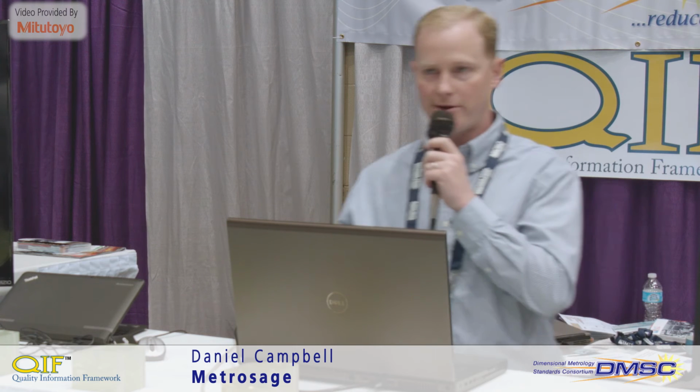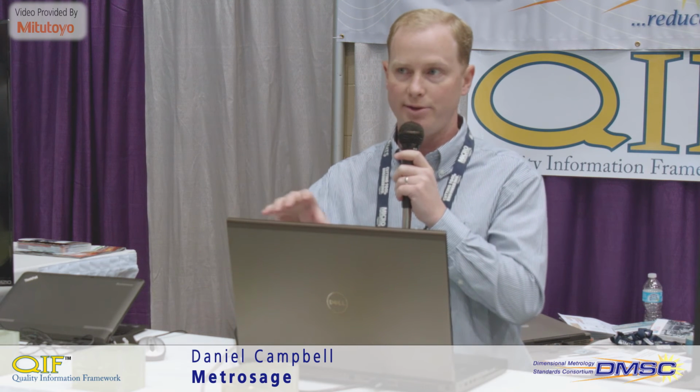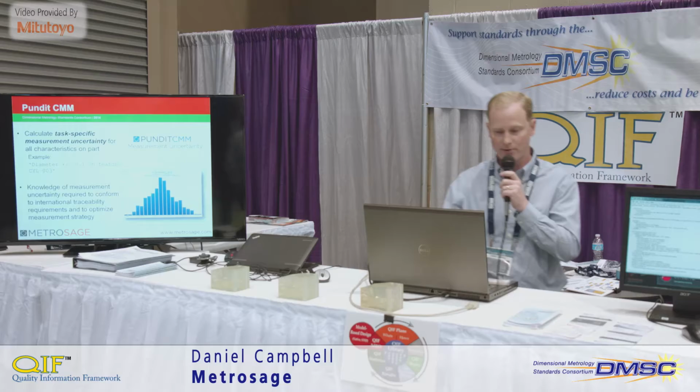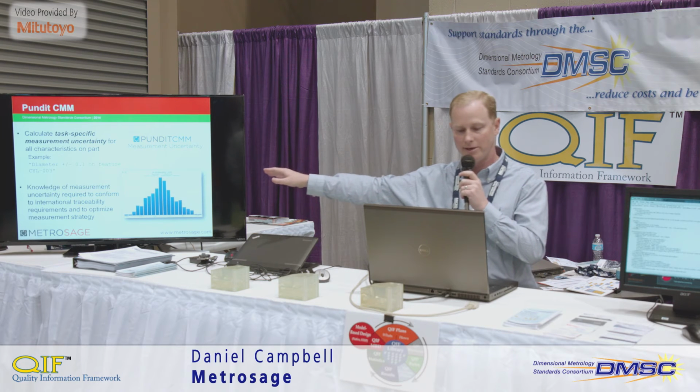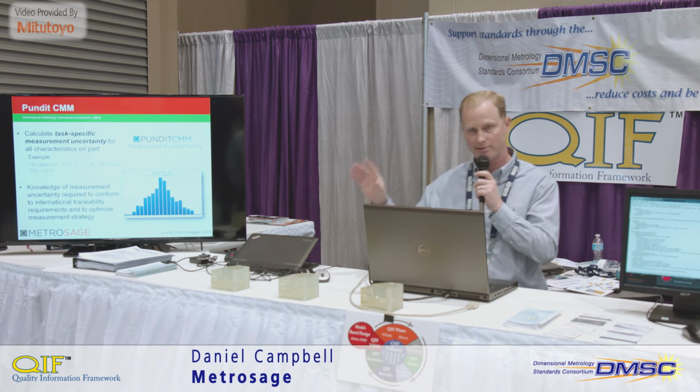Now, a little bit of background on what Pundit CMM does. We calculate task-specific measurement uncertainties associated with your CMM measurements. So an example would be right there, a diameter tolerance on a specific feature. We would have a measurement uncertainty for that value.